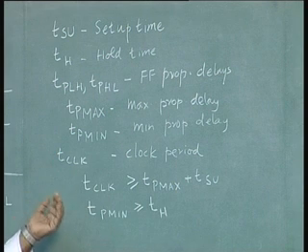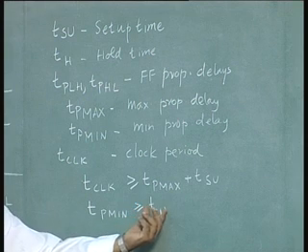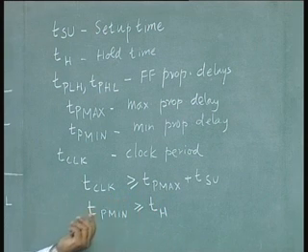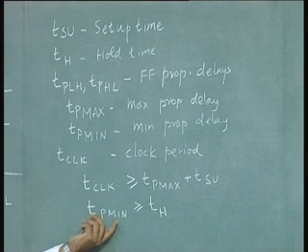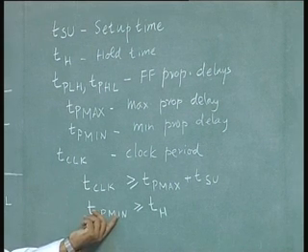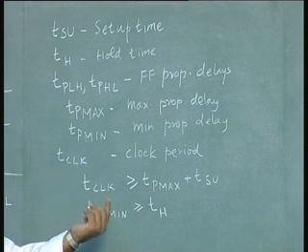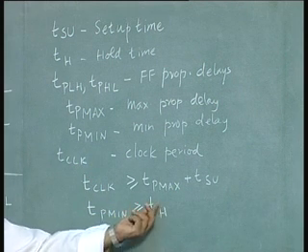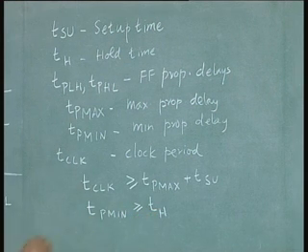The valid data at the input of the flip flop should not change for a duration of TH after the clock edge, but after the clock edge TP minimum is the minimum period at which the data is going to change, and if this is immediately fed back as the input, the data would have changed before TH has elapsed. So, that is why this additional condition.